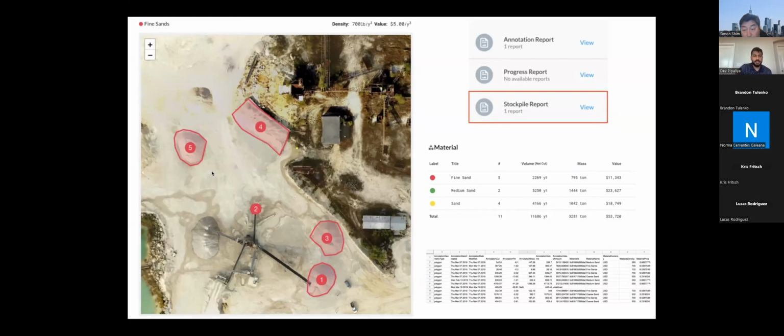But once you have drone data, you can just click around the stockpile and see how many cubic meters it is. Then you can use that number and divide it by the number of trucks you will probably need. That can be really useful when it comes to a site.